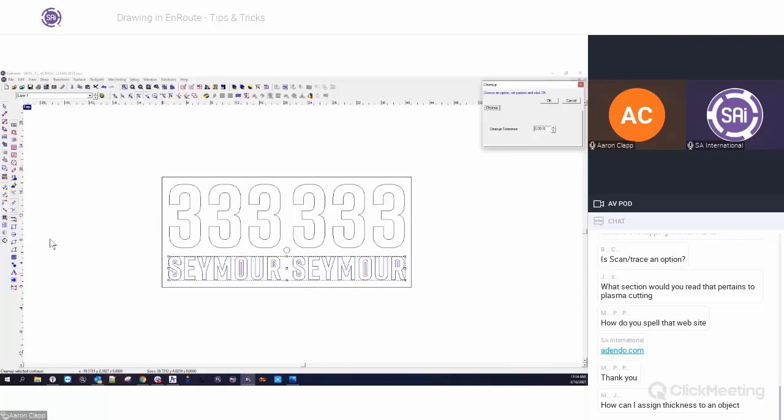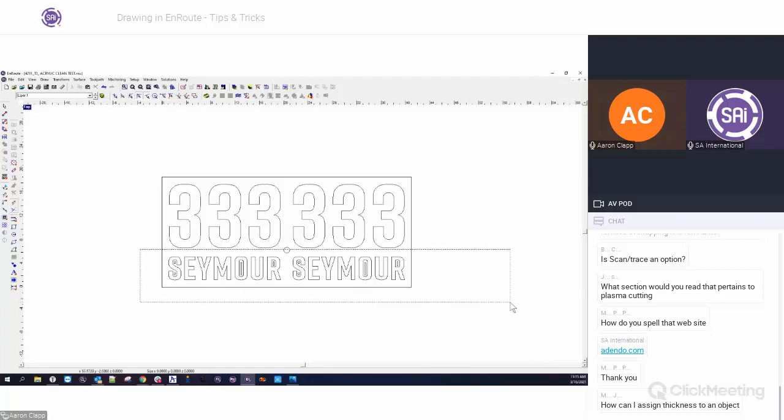Here's a little shortcut for it. In this case, it didn't allow us to remove a bunch, because I think I already cleaned this up before and saved it. Unfortunately, I didn't go back to the original file. It was a lot worse when I first started, in the thousands of points, and then we reduced it way, way down. So that's a way to reduce points, and sometimes it can also clean up little overlapping spots if they fall within that tolerance range.